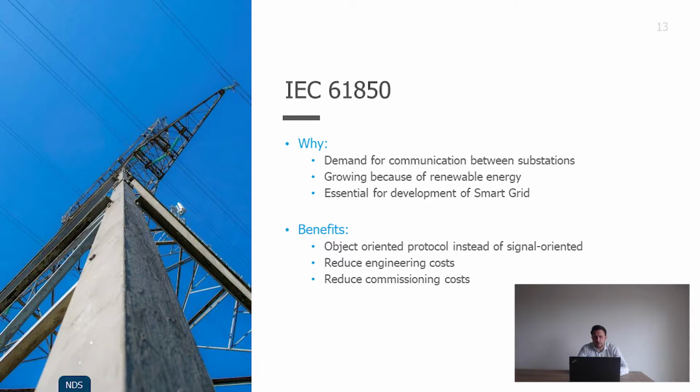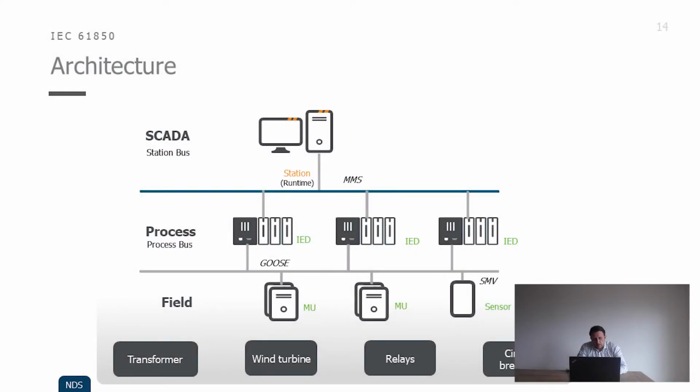Client applications therefore no longer need to manually configure each point they need to access, because it can be retrieved directly from the device or imported from a configuration file. So therefore the cost on configuration and commissioning the IEC 61850 devices is reduced, because it doesn't require as much configuration as legacy devices. Now let's have a look at the network architecture.